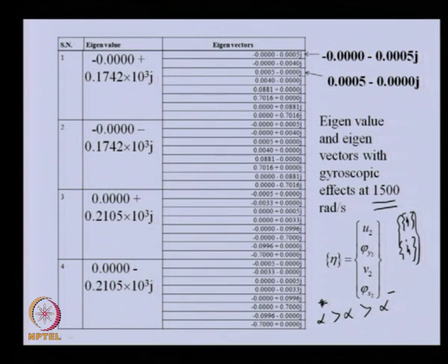But when we will consider the damping, especially like fluid film bearing, we will see that both quantity will be complex, and then plotting of the mode shape will be more difficult in that case. Now, we will take up another case in which we will be mounting a flexible rotor on fluid film bearing, and through one example directly we are explaining how the fluid film bearing elemental equation can be clubbed with the finite element equation of the shaft system.